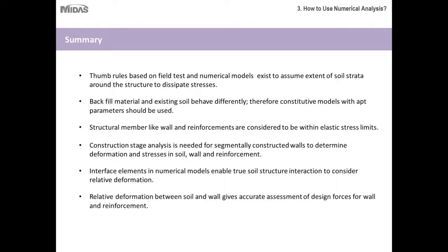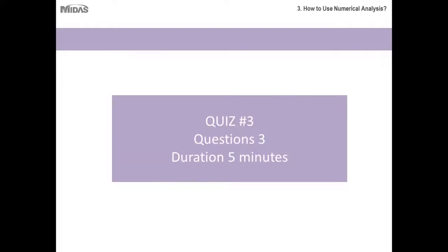And the interface elements in numerical models enable true soil structure interaction to consider relative deformation. And relative deformation between soil and wall gives accurate assessment of design forces for wall and reinforcement. And finally, interface properties are dependent on soil type, and inputs can be obtained from the field test.